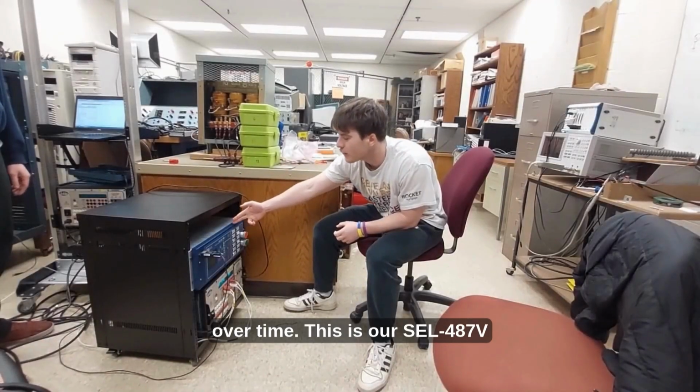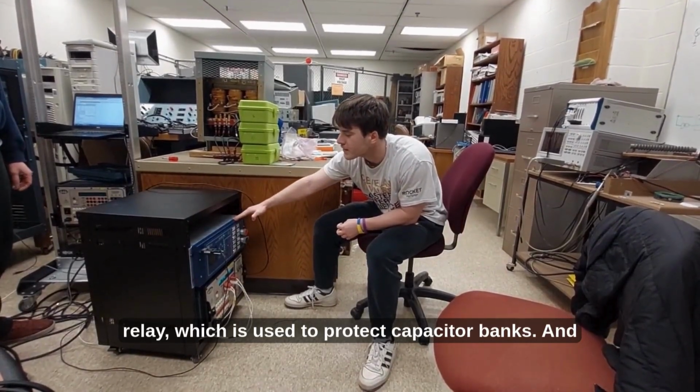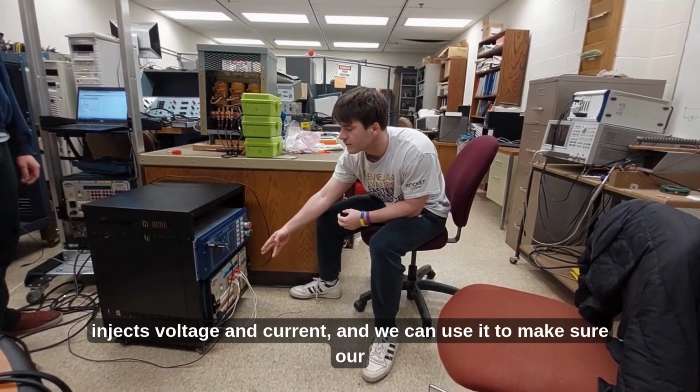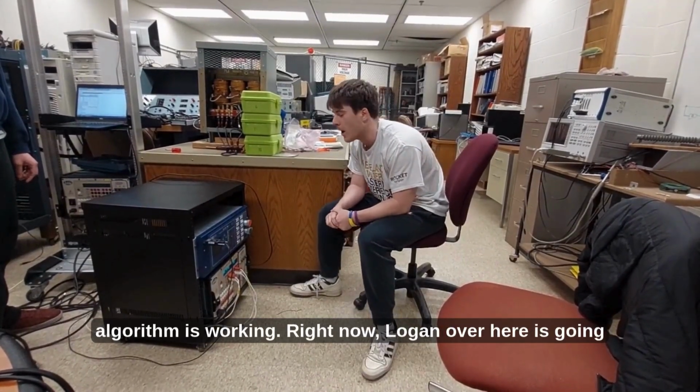This is our SEL 487V relay, which is used to protect capacitor banks, and our Doble test kit, which we use to test our relay. It injects voltage and current, and we can use it to make sure our algorithm is working.